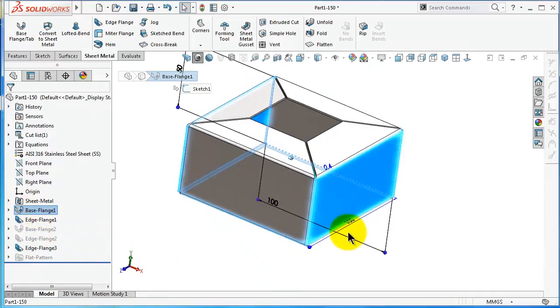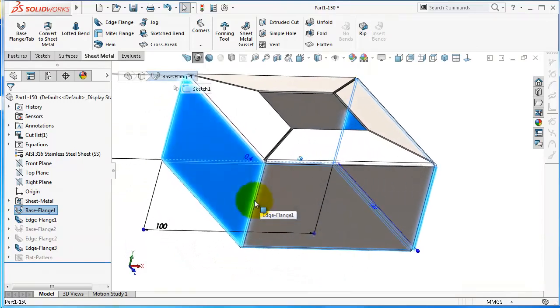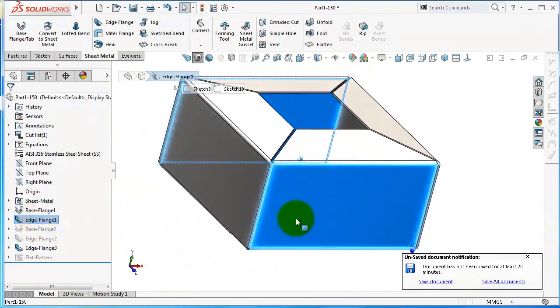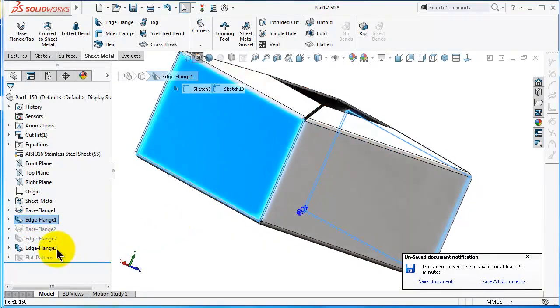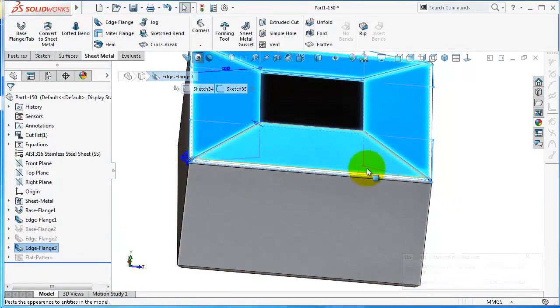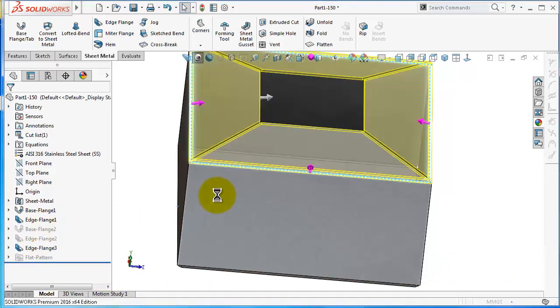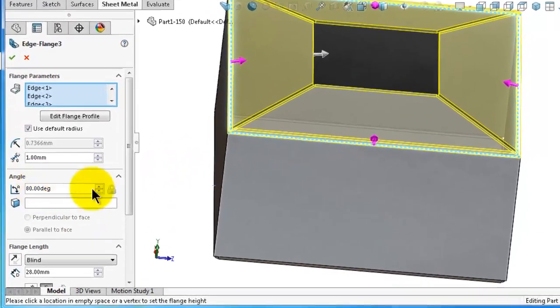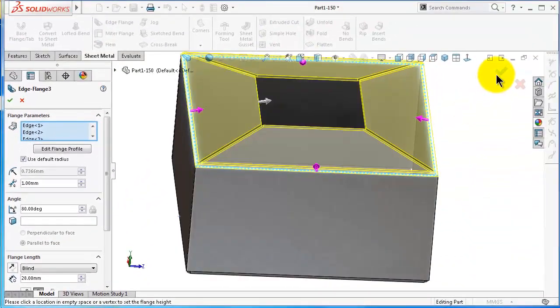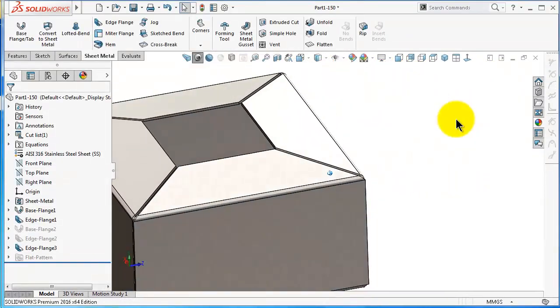The first is a flange, a U shape, as you notice here, and then we made the edge flanges over here and here, and then we made the miter flanges over here by the edge flange. And as you remember, with the third flange, we have an angle of 80 degrees. So let's see how to create a similar box but with the miter flange.